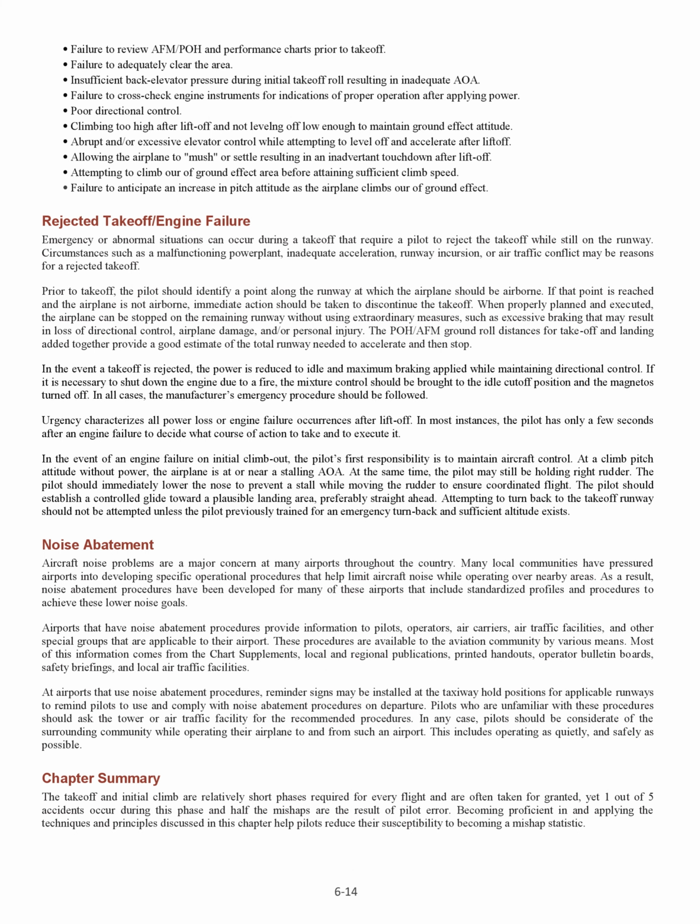The pilot should establish a controlled glide toward a plausible landing area, preferably straight ahead. Attempting to turn back to the takeoff runway should not be attempted unless the pilot previously trained for an emergency turnback and sufficient altitude exists.